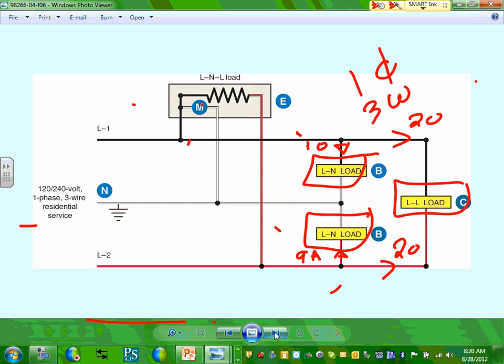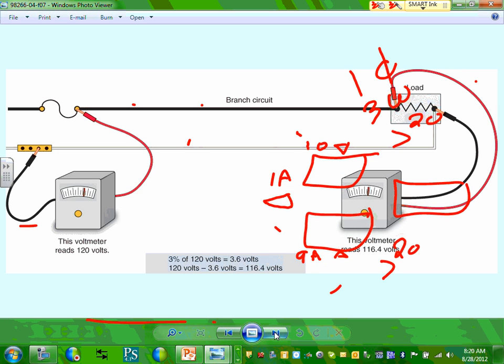So I have 10 amps, 9, 9, 10. What do you think the neutral is going to see? The neutral is going to be 1 amp. So do you think the line to line will contribute to the neutral in any way, shape, or form? No. Can you see, if you tie an equipment line to line, they don't contribute to the unbalanced neutral. Can I have thumbs up, Chad? We know line to line would not contribute to the unbalance of the neutral.